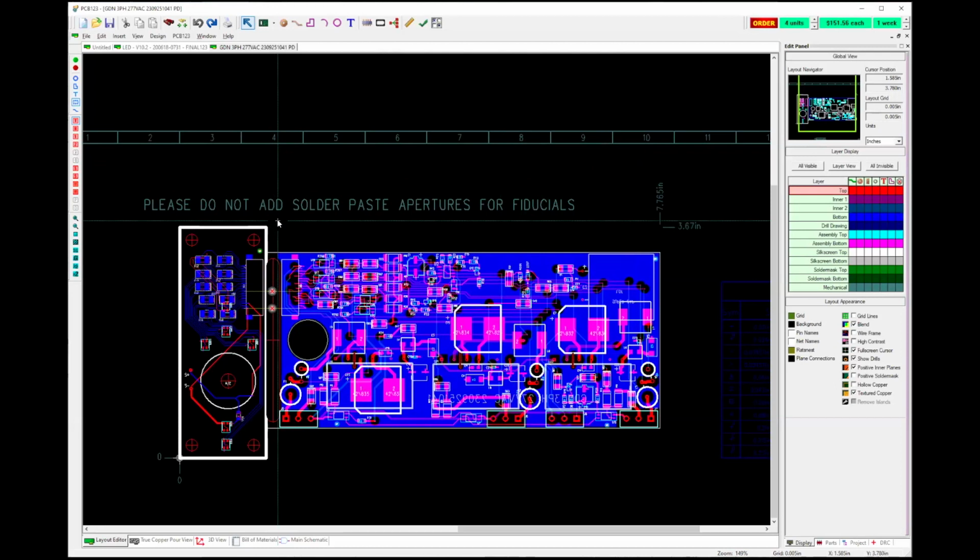I can't remember exactly the details. We did it. It was fine. The boards came out just fine, but it's not something we actually went to production with, and it really wasn't necessary for the boards to work. Again, if you're running a lot of power and you want to get those heavy layers on the inner layers, you can do that, but it's still going to rely on the thickness of the traces on the outer layers, so it's not always that important.